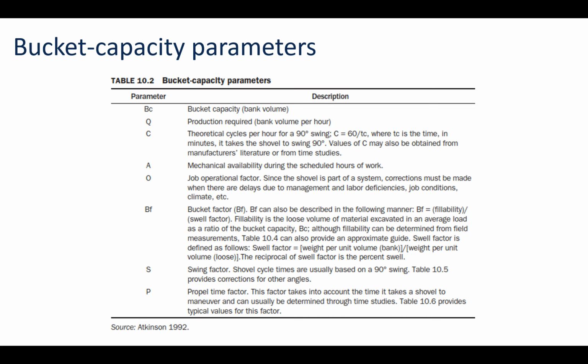The bucket fill factor can be described as the fillability divided by the swell factor. Fillability is the loose volume of material excavated in an average load, so how much you load up in an average bucket as a ratio of the capacity. So how full can you get the bucket is what it's trying to say. And so you can determine that from field measurements, but there's also going to be tables here in this presentation that can give you an approximate idea.